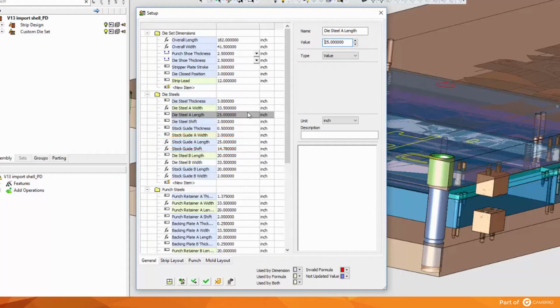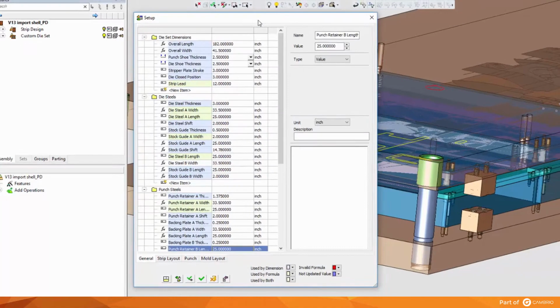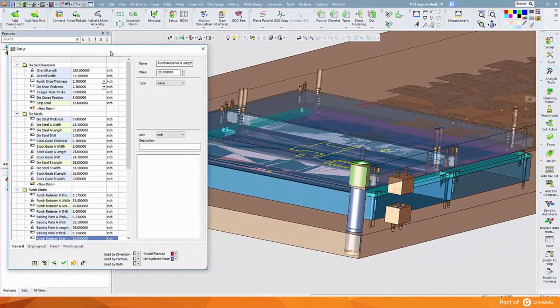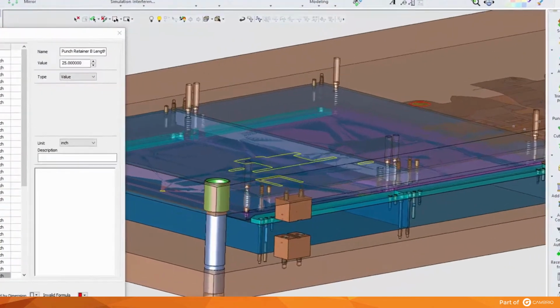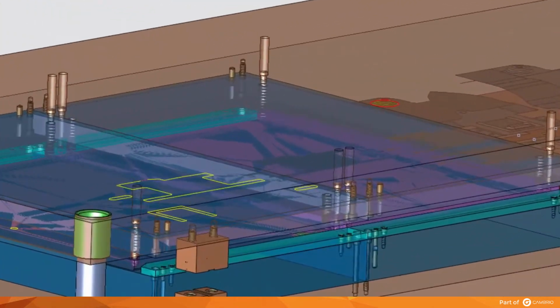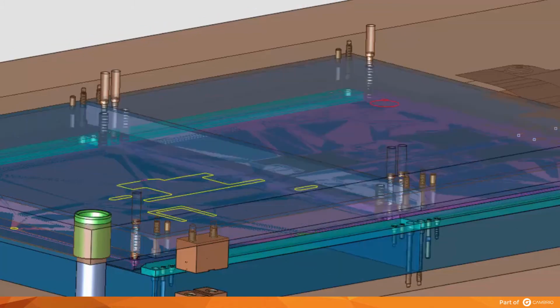This particular die set has two stripper assemblies. Another die set could be saved with one stripper assembly, no stripper assemblies, a bridge stripper. It's all a matter of what the preference is for the designer. A similar relationship was used between the retaining plates and the backup plates. Since the width and length of the die plates are being changed, when the die is regenerated, the location of assembly screws and dowel pins will likewise change. They're tied geometrically to the corners of each of the plates.